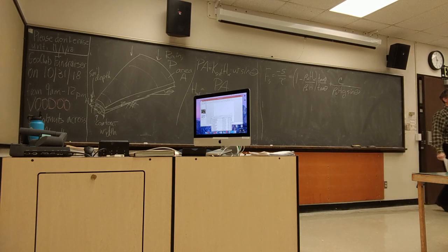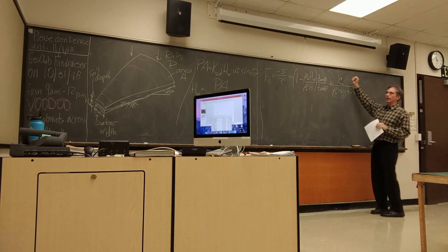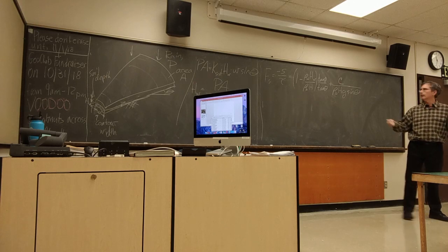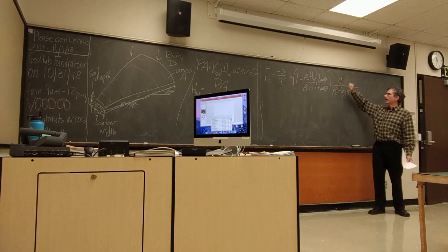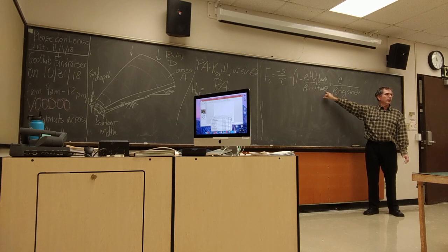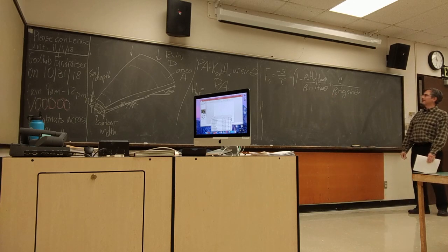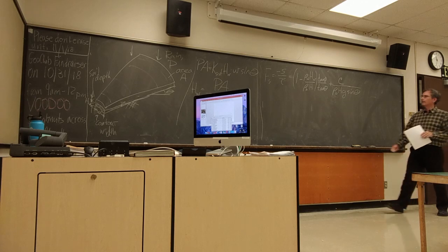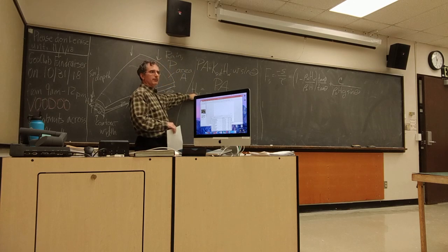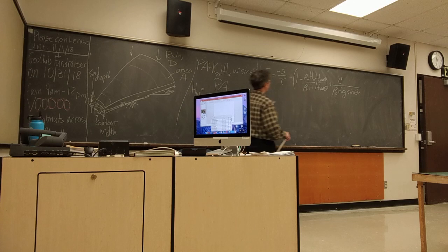Now, when we were coming up with our slope classes, we said even with zero cohesion, there's a class of slopes that will never fail, given a value of phi. And so in that case, we said, okay, let's set cohesion to 0. And with phi at 37 degrees, we came up with theta of 21 degrees. So now I can do this, right? If I've got precipitation, contributing area, the rest of it, I can find out what my level of saturation is in the soil. I can plug that into here.